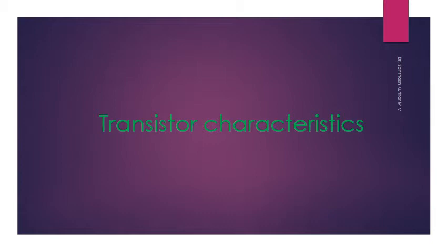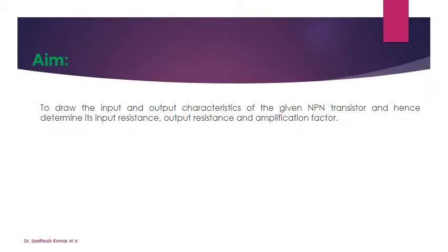In this video, I am going to demonstrate the experiment called transistor characteristics experiment. I hope this video will help you understand this particular experiment easily. The aim of the experiment is very simple: to draw the input and output characteristics of the given NPN transistor and hence to determine its input resistance, output resistance and amplification factor for the respective transistors.